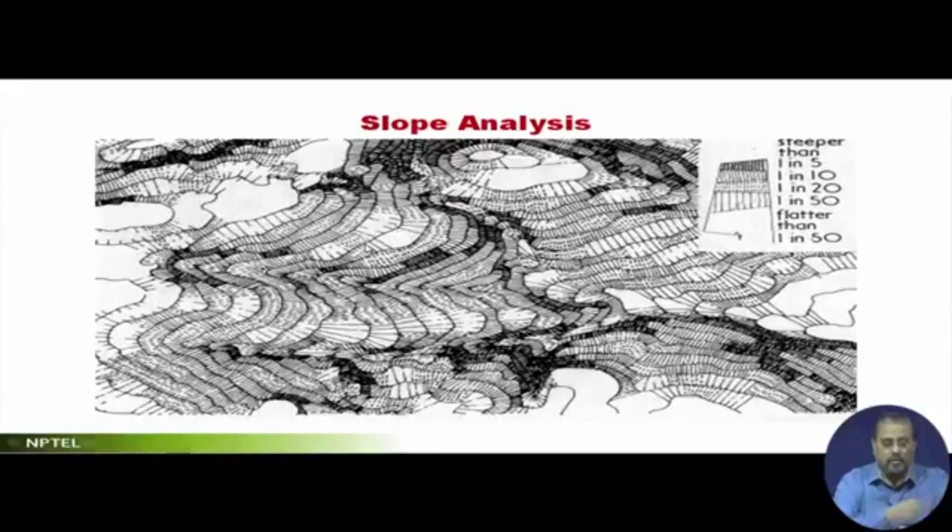You know what is done is, if you try to represent this, you can do it with color or with hatch patterns. If you do it with color, wherever it is steep, you give a darker color in the monochrome. Say you select any color and find out the monochromatic range of that, and wherever it is gentler, you give a lighter chrome of that, and wherever it is steeper, you give the darker chrome of that, by which if you fill up the whole area, then you can straightway indicate which portion is dark, which portion is steep, and which portion is gentle.